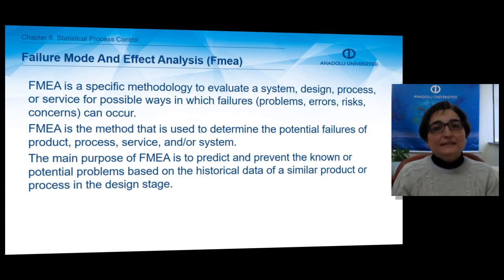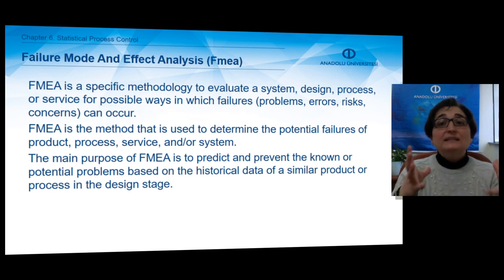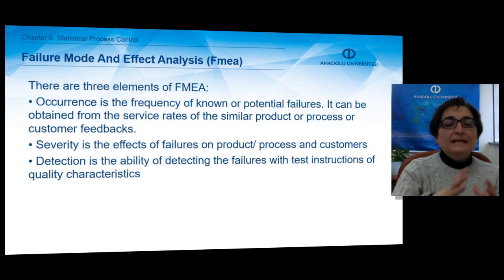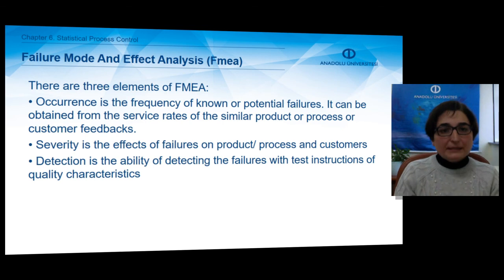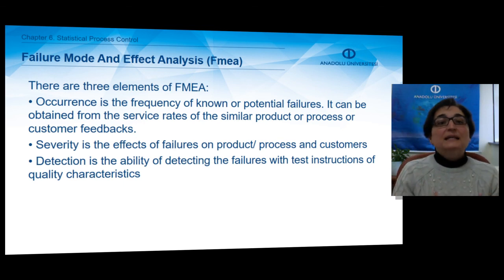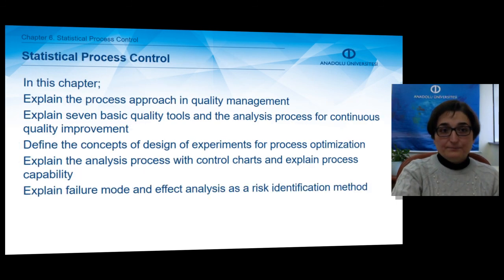Failure mode and effects analysis is a specific methodology to evaluate a system, design, process, or service for possible ways in which failures can occur. There are 3 elements. Occurrence is the frequency of known or potential failures. Severity is the effects of failure on products and services. Detection is the ability of detecting the failures.